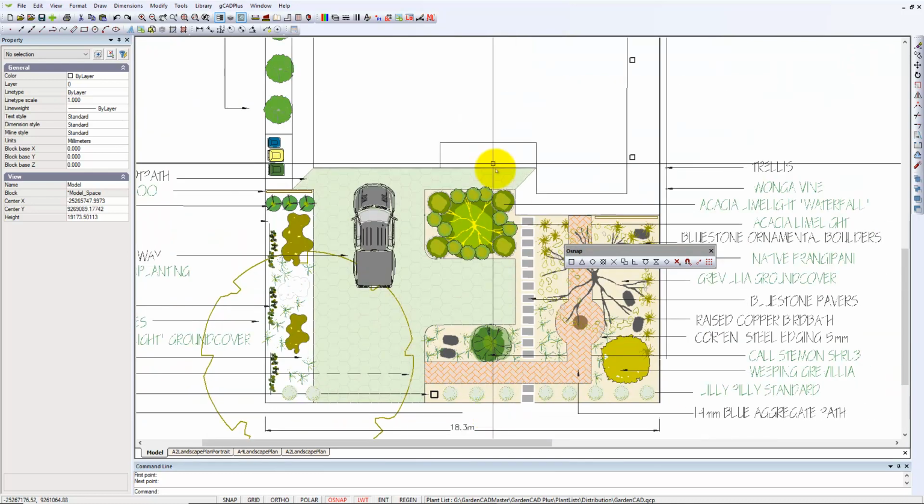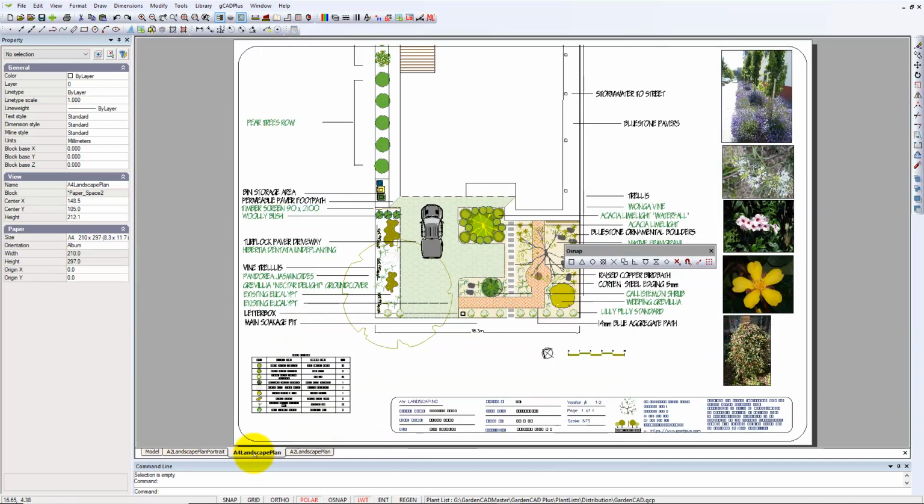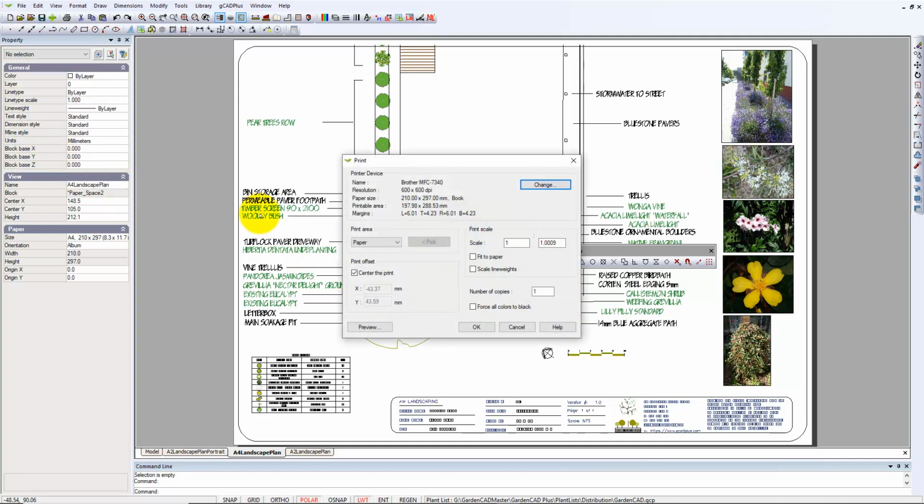Well, if you work in layout space, use standard symbols and set line thickness to by layer, you can manage to print very easily and print on different size sheets just by changing one variable. Let me illustrate. Here's A4 landscape. I've got line weight turned on, and I'm going to print. And let's imagine I want a high quality print.